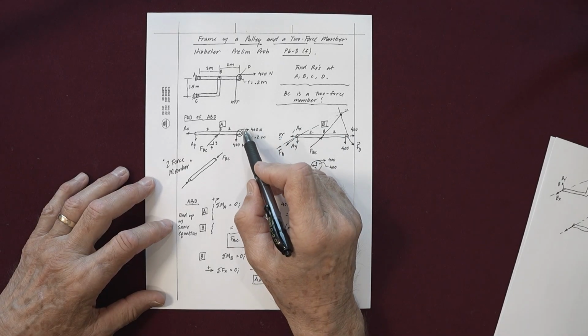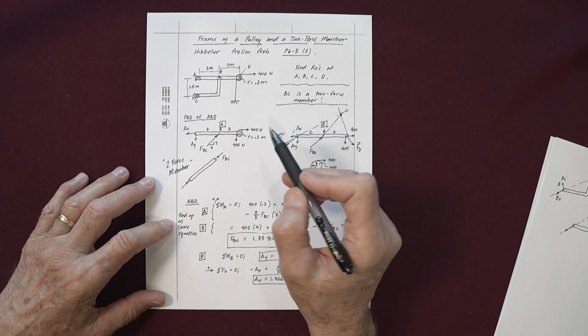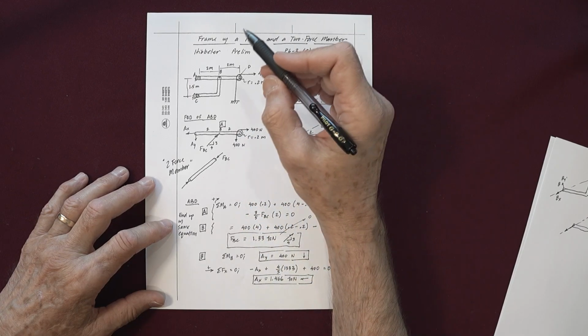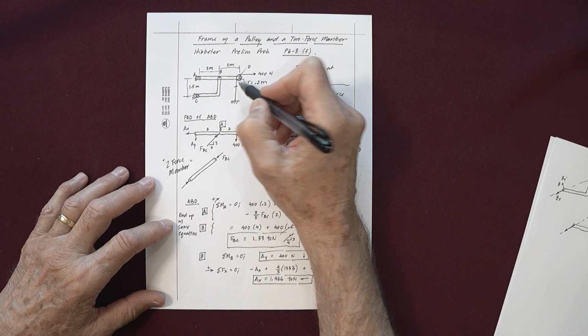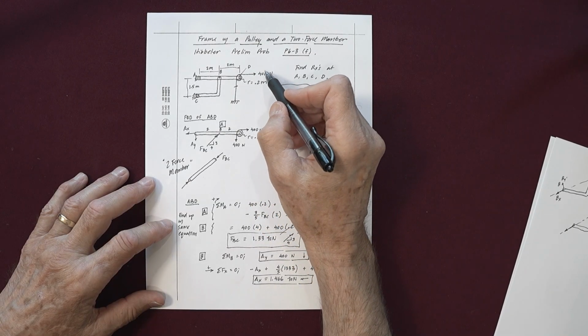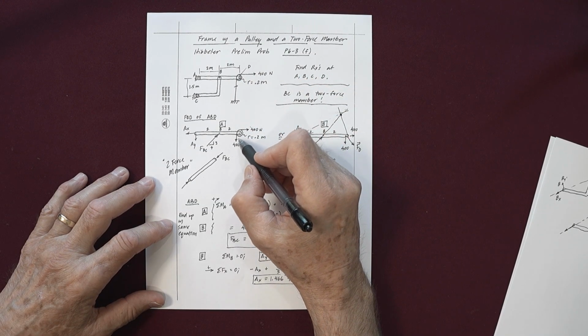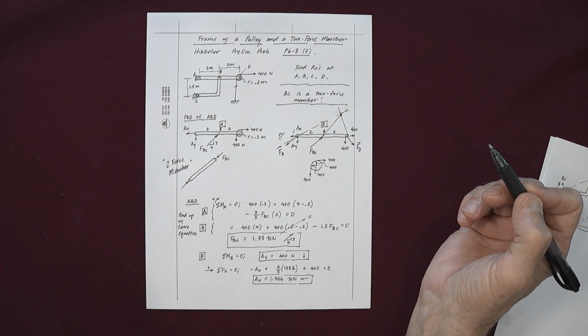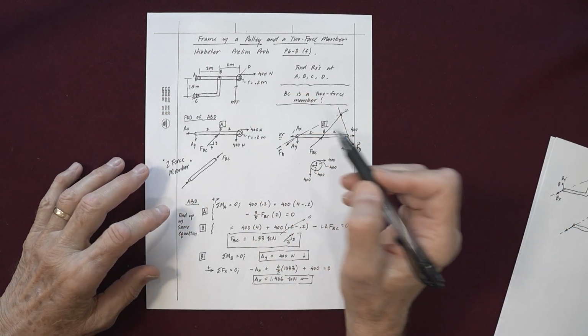Okay, so let's talk about this pulley. So we talked about the 2-force member. We've got the single force there. So this pulley. When I'm drawing a free body diagram, I cut this cable, and I cut this cable. And there's a 400 Newton force in this cable here and here. And so I can leave those forces on the pulley just like that. And I can work the problem that way, leaving those forces on the pulley.